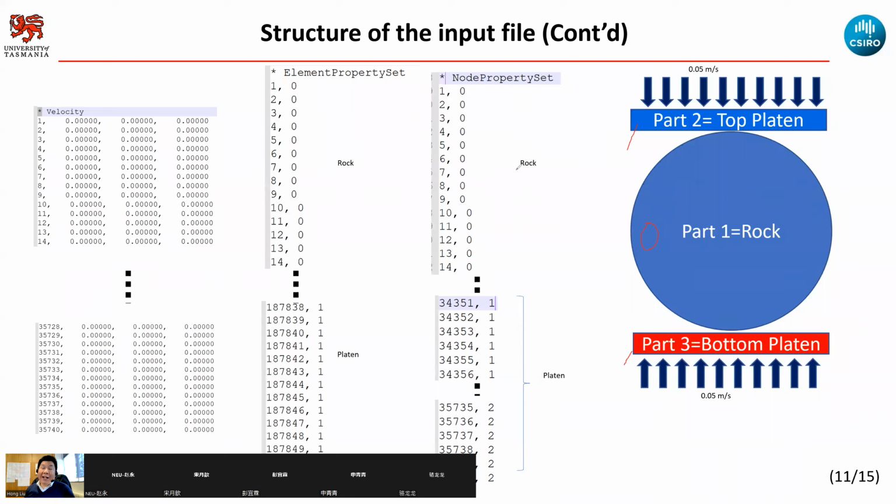This is a little bit different compared with the two-dimensional modeling. For the two-dimensional modeling, I have an element property and a loading property, and actually I mix them together. So I have the label, which is continuum, then 0, then 1. For the two-dimensional modeling I have this, then 3, and then 4. For the three-dimensional modeling, we separate them, so we have the element property, the label, and the loading property separately. That's why you see it here.